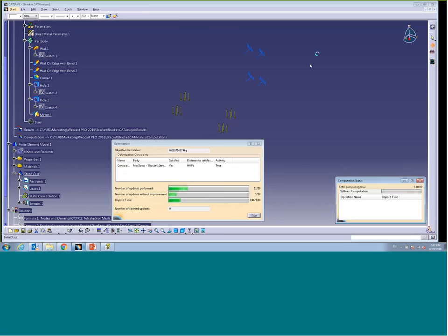Yeah, so it's the 12th iteration right now. Whenever you have FEA in the loop, it always takes longer time. And if you want to do something like that with something that takes quite some time to compute, there's an option to create a batch, which is you set up your model, prepare parameters, etc., and then just run it overnight using batch mode. So that's something that could be quite useful. But hopefully this one runs. So what is it, just over 1 minute? If I'm not mistaken, it should take about 2.5 to 3 minutes, so hopefully.